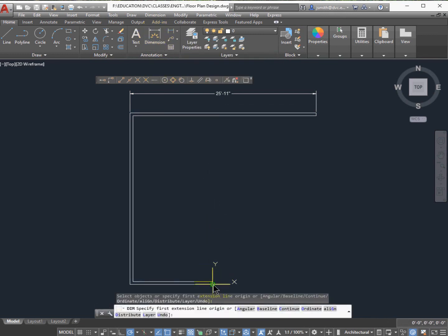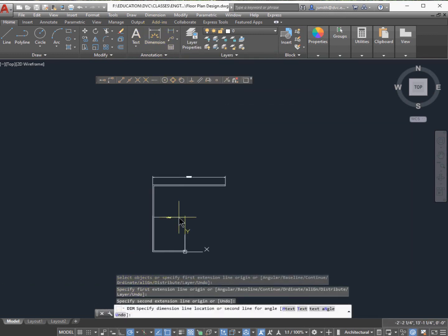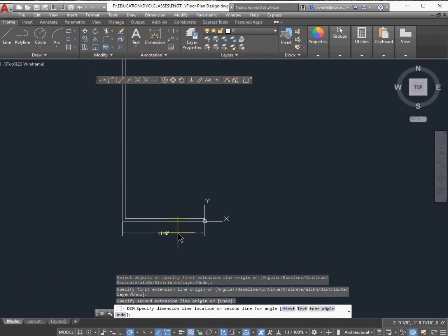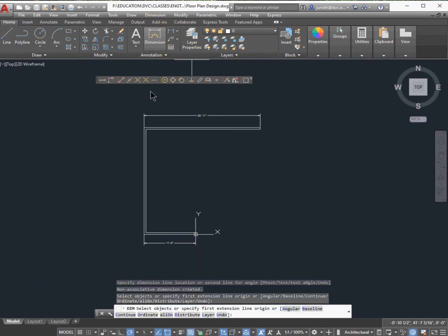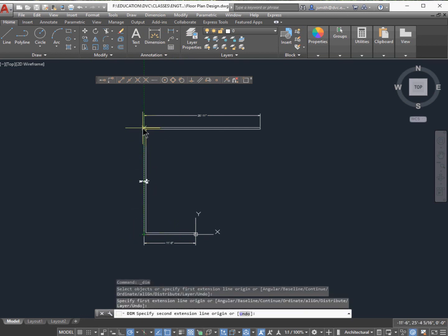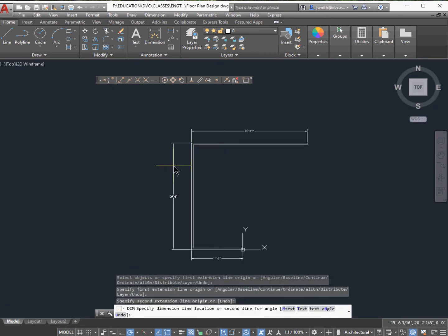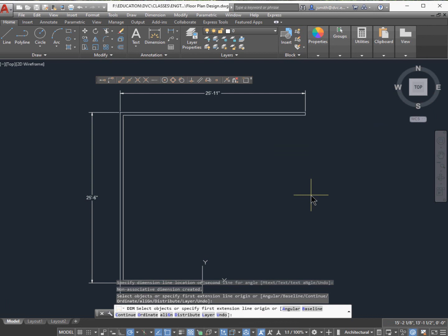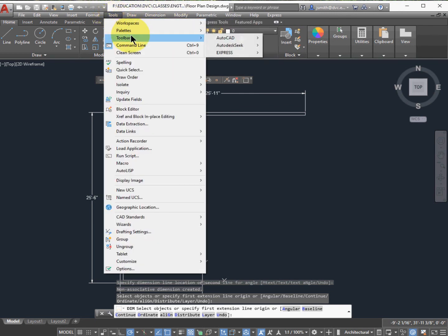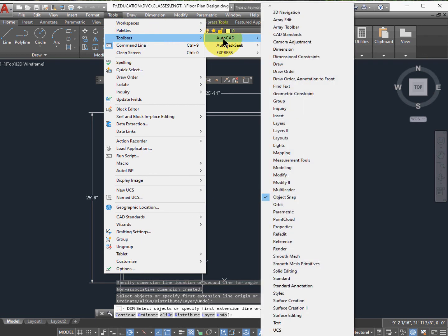It looks good. So now let's go ahead and just confirm the dimensions of the wall here. I'm trying to do this in a manner that reflects what my final drawing is going to look like. All right, so that should be 25 foot dash 6. And then what we're going to do is add that little gap for the door. It's a 3-foot gap. In AutoCAD, we've got this object snap. And so the way this works is you go to the object snap.